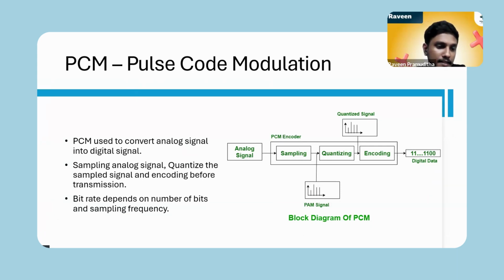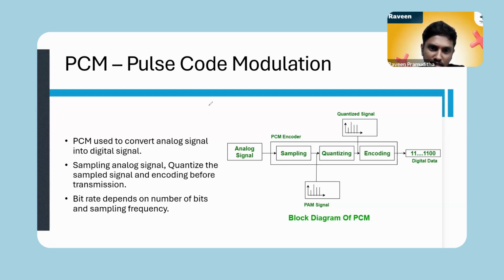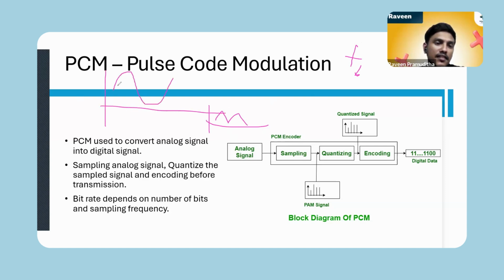What we are doing here is we input our analog signal in the input section. Then we sample that signal according to some sampling frequency, like Fs. So I input this sinusoidal wave. Then I can sample this audio signal according to my sampling frequency. Then you send this sampled signal to the quantizer. There are two types of quantizers, linear and non-linear quantizers. Based on energy wastage, we sometimes use non-linear quantization levels, but the output is like this.